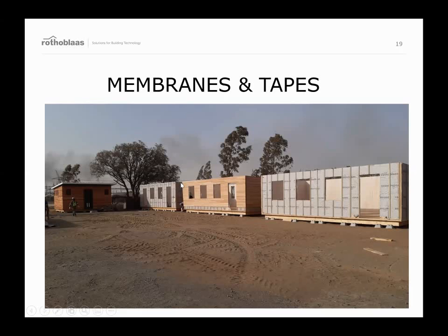For horizontal cladding, you always want vertical battens. If you wanted to put vertical cladding, you would have vertical battens, a horizontal counter batten, and then your vertical cladding again. This is to prevent any moisture sitting directly on the face of your waterproofing membrane where it can't go anywhere.